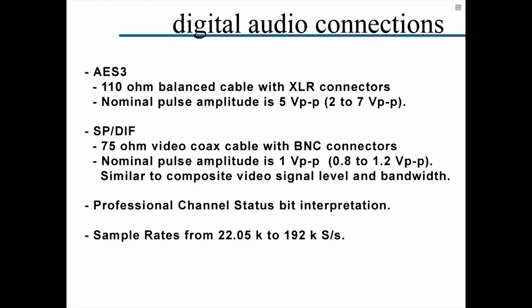There are two digital audio connection standards in common use today. AES-3, formerly called AES-EBU, which was developed by the Audio Engineering Society in conjunction with the European Broadcast Union, and SPDIF, which was developed by Sony and Philips. The former is found mostly in professional applications, where the latter is generally used in consumer applications, though a fair amount of application crossover is typical.